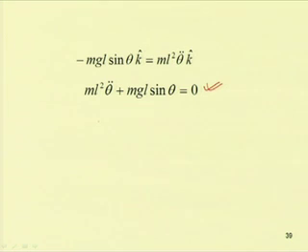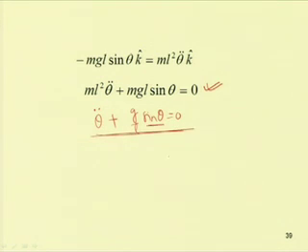So, what we obtained before, the equation of motion, is theta double dot plus g by L sin theta equal to 0. One can write the nonlinear equation of motion by expanding the term sin theta equal to theta minus theta cube by 6. In this way one can write the equation of motion. As we have discussed previously, one can obtain the potential well and study the response of this system qualitatively.